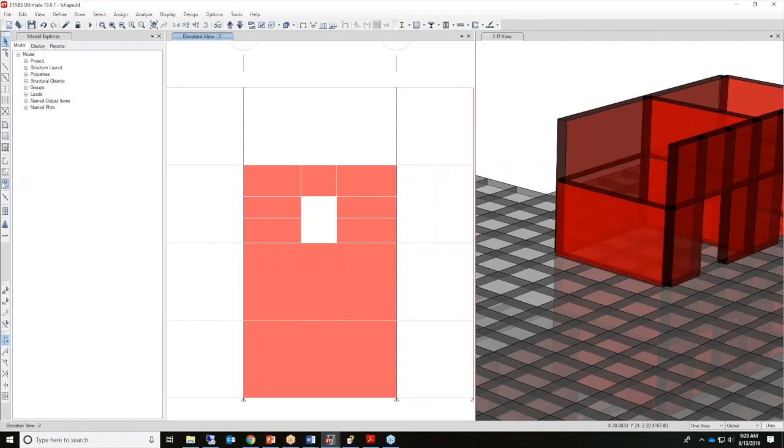That's one way to do it. Or there's something called the draw wall openings tool, which gives me the ability to drop in an opening in any location. I'm just going to arbitrarily generate one here. So I dropped in an opening in the specific wall. But the question is, okay, you put an opening in the wall, what about meshing? The answer is yes, I need to mesh this wall as well. You can't just put an opening in the wall and not have it meshed for proper load distribution.